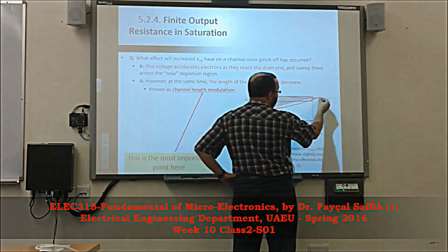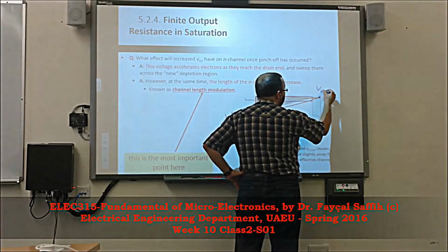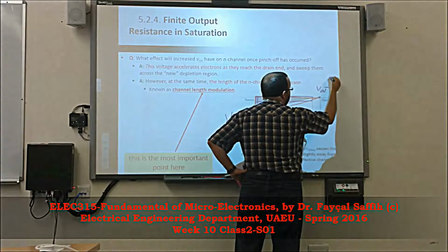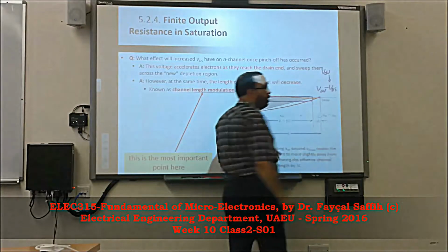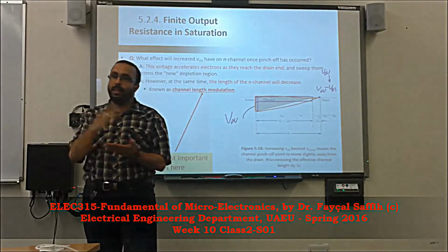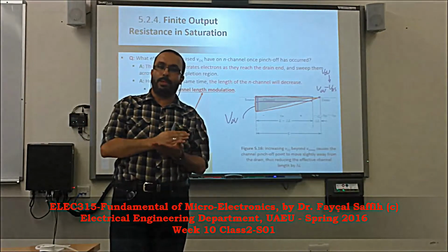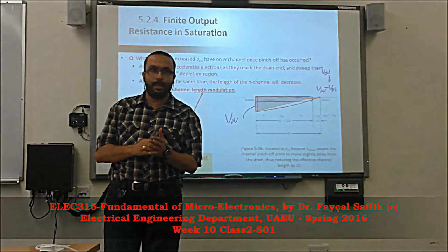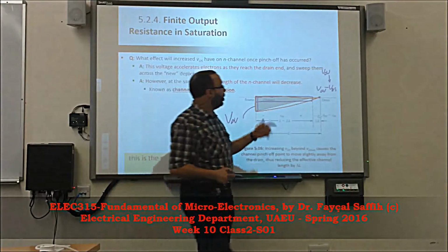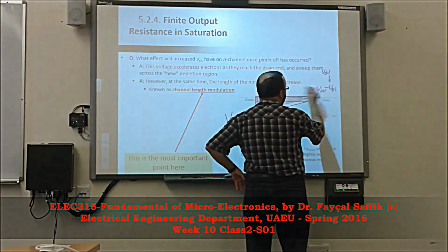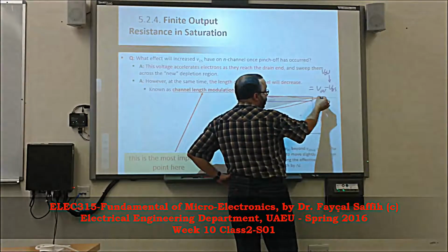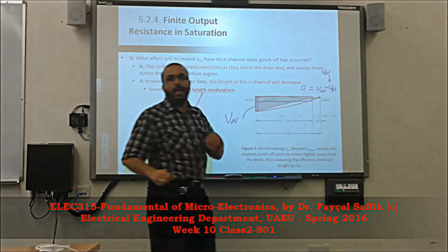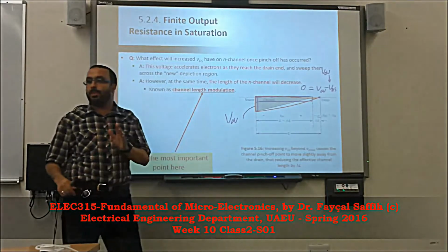So we said that here the voltage is going to be overdrive minus what? Minus VDS, and VDS in this case is V overdrive. That's where the pinch off starts. It is the limit, or the border, between the triode and the saturation. Got it? Good. So the effective voltage on the channel here is going to be 0.